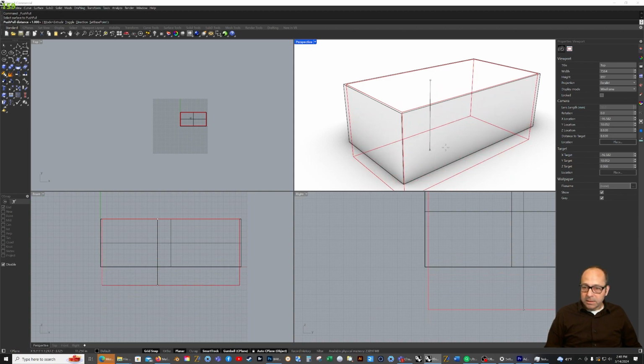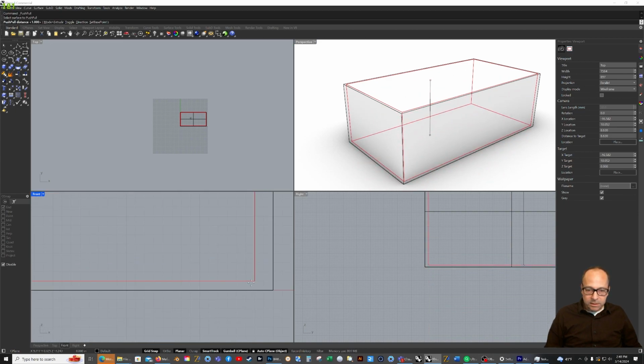Now it's going to be very hard to know exactly where we are here. Now our grid snap is still on, but it's hard to get the exact thing you want in the 3/4 view. So just zoom in to this front view. I want it an eighth up. Like I say, the grid snap is still on. If for some reason the snaps were on, it may try and snap to like this outer corner. So sometimes you want this off, sometimes you want it on, depending on what you're doing.